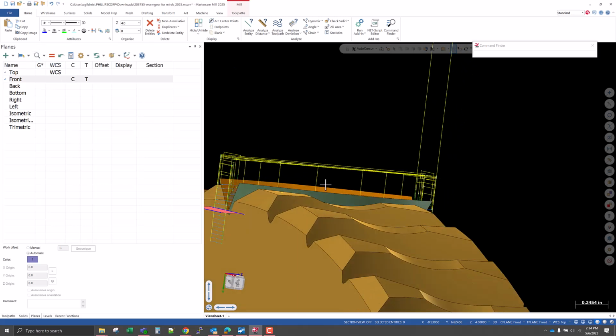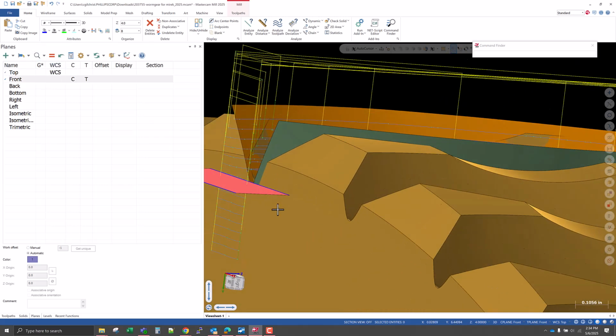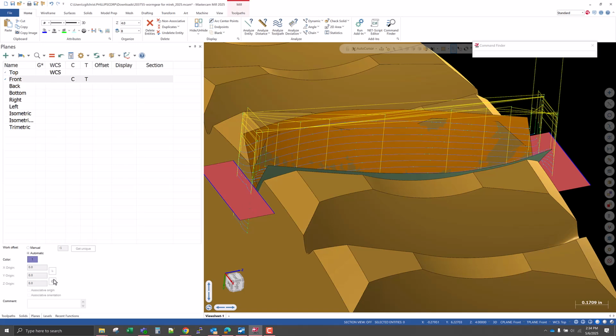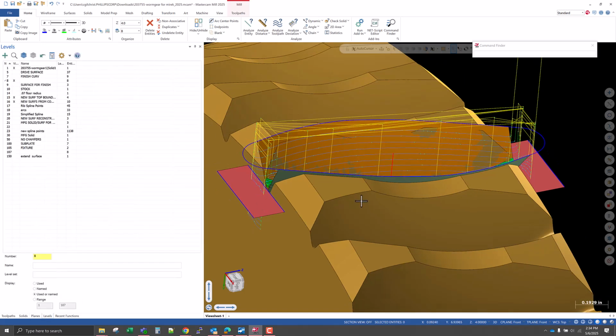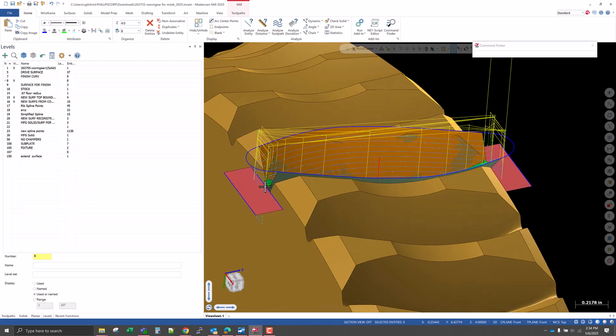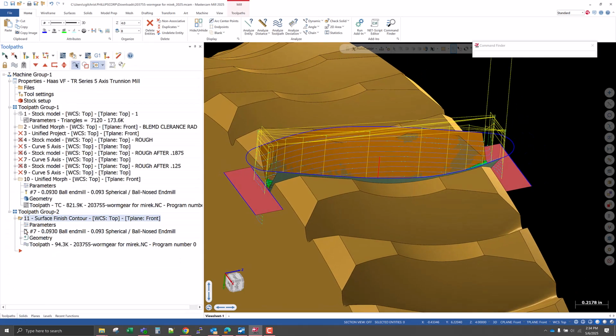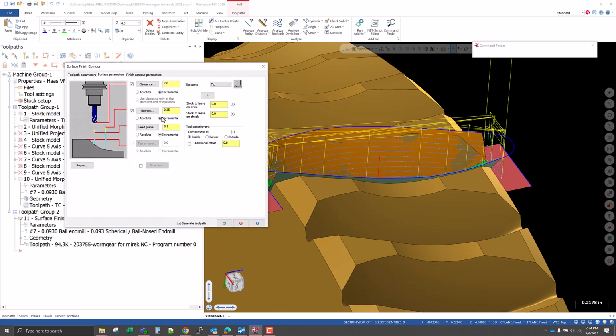All right, so now we've got this place where our toolpath is kind of diving in because of our boundary, right? So our boundary's up above, and I'm just using Alt-E, Alt-Echo on the keyboard to set that. So now I can go back into this surface finish contour.